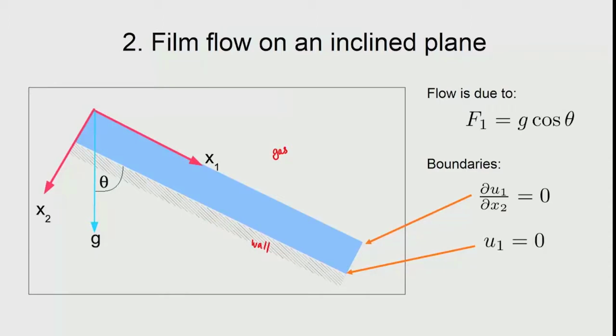So, if this is the problem, then how do we arrive at a functional form for the velocity as a function of distance? We choose the coordinate system so that the velocity is a single component. So, we see that velocity should be only along the x1 direction. So, the flow is basically u1, and it should be a function of x2. This way we choose, so that the problem is simplified.